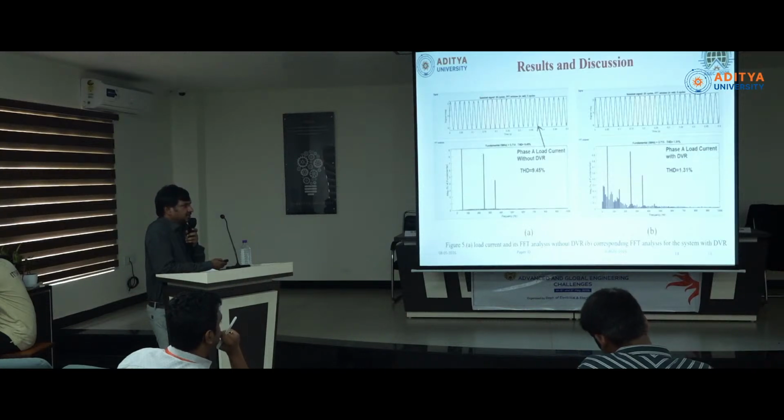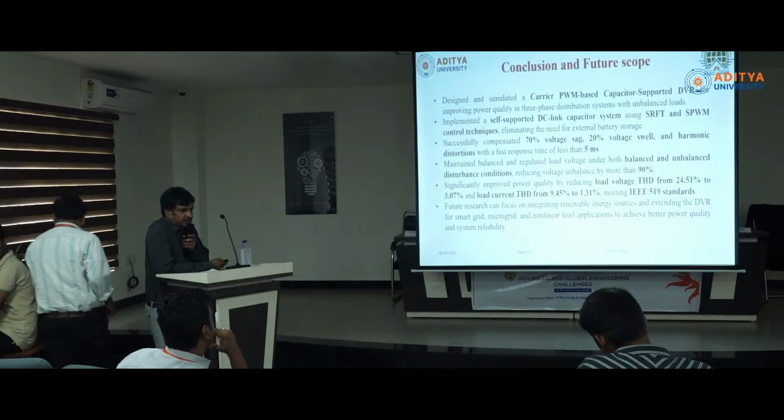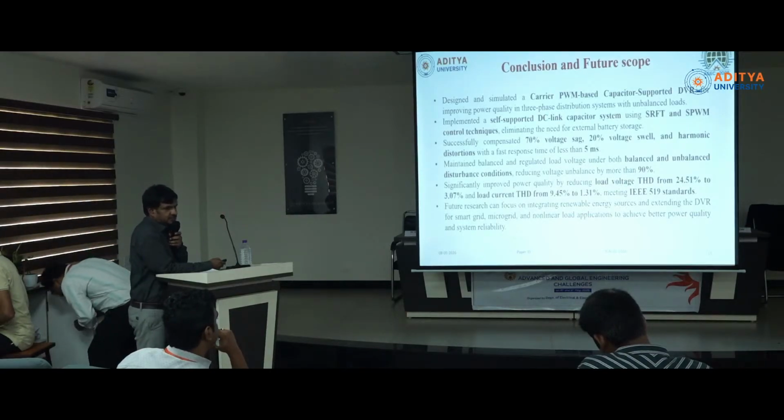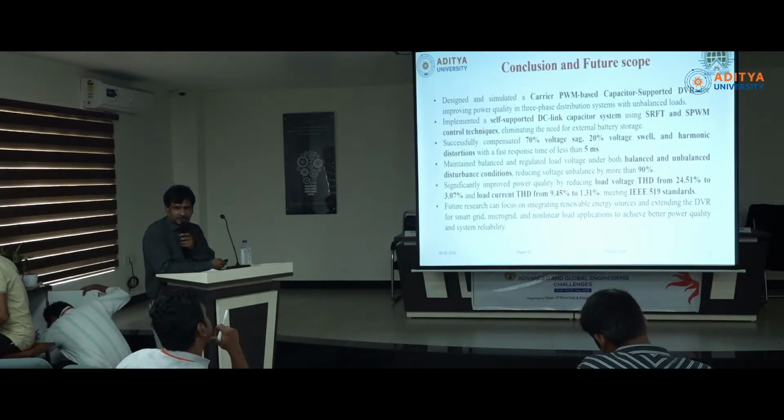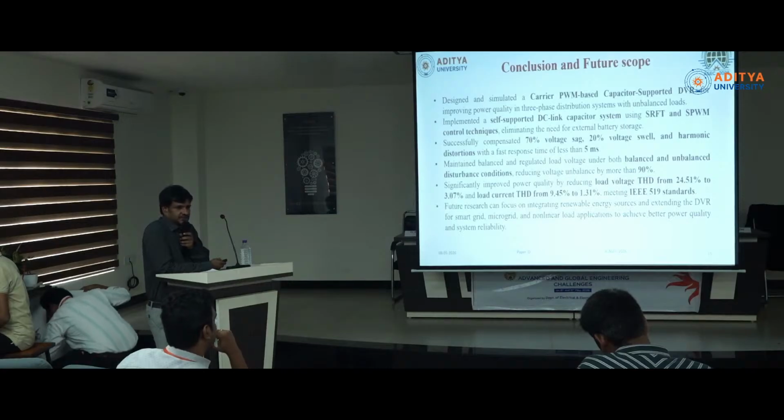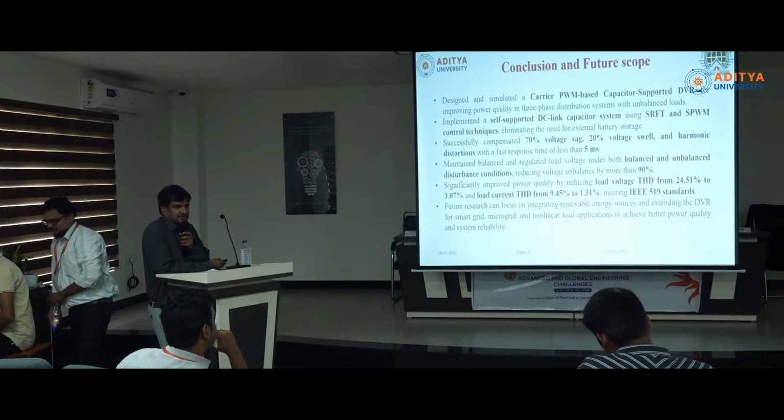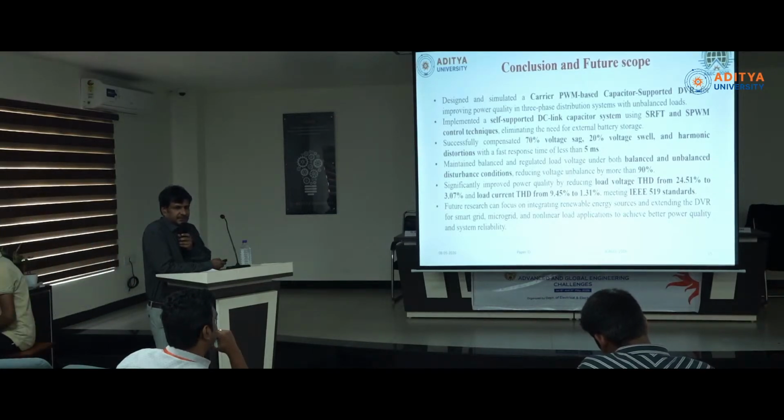And the THD waveforms. My conclusion is that by this proposal we can use the distribution system to get some power quality improvement at the distribution side. Even if any distortion occurs on the grid side, whether unbalance, sag or swell, the voltage and current can be made smooth and you can protect the devices at the load side.